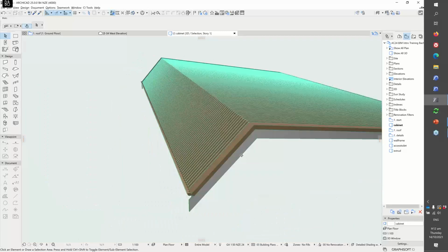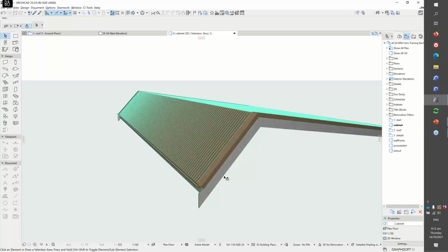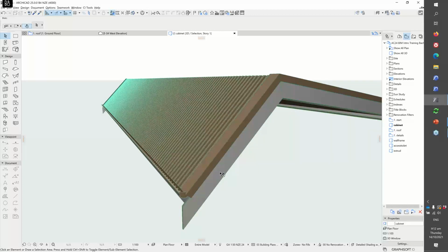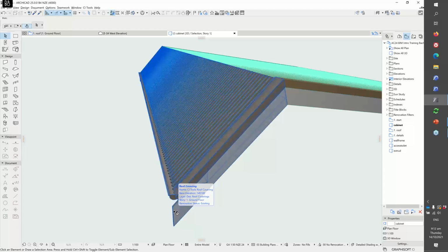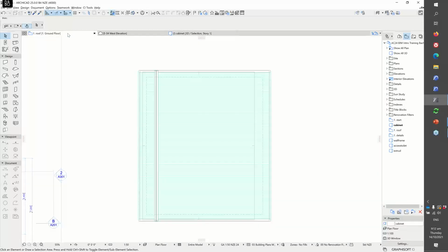And because, as I said, we're able to detect the edge of the roof now, we can also have the covering match the roof edge rather than just being vertical like it traditionally has been in the coverings tool. We had a lot of people ask about the ability to match the roof edge, so you can do that now.